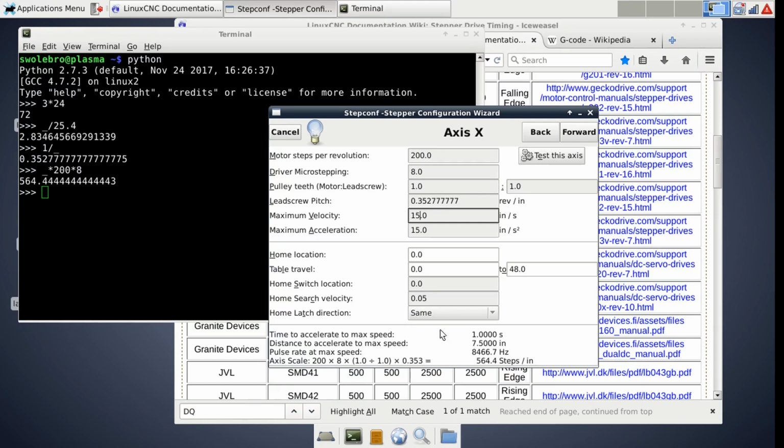So down here, we set the work envelope. And if you have home switches, we can tell LinuxCNC where they are. Usually for a gantry, you define everything in positive coordinates with homes at 0, and there they double as a limit switch. If you're doing a mill, you might have both positive and negative X and Y with a home in the middle. So that would mean you have a limit at either end and a home, for 3 switches per axis instead of 2. And then your Z for a mill might be positive or only negative, depending on how you like to do your CAD.